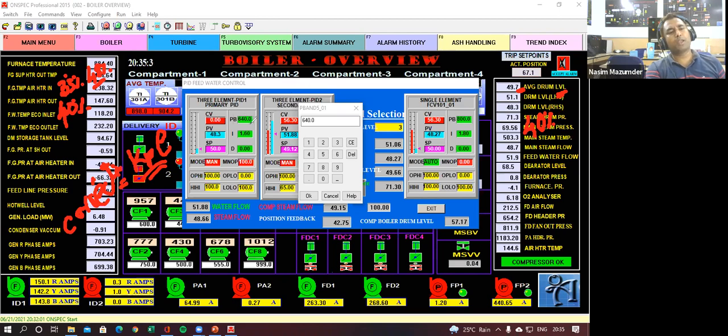So it took me approximately 1 or 2 days to sort out this problem, and it was completely clear observation, and completely hit and trial. So trial and error means what? You cannot go arbitrarily and do it. You have to observe what kind of problem you are facing over here, because the moment you are increasing the process band, it will be multiplying the error signal.